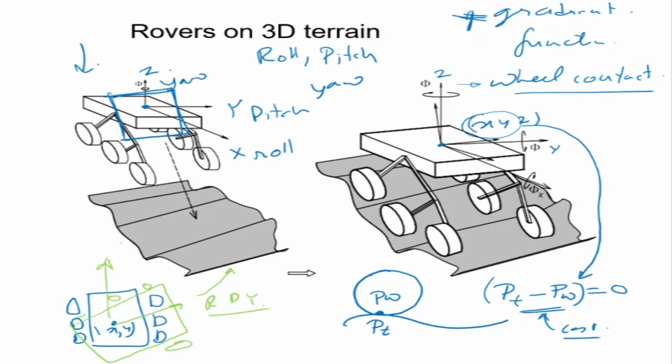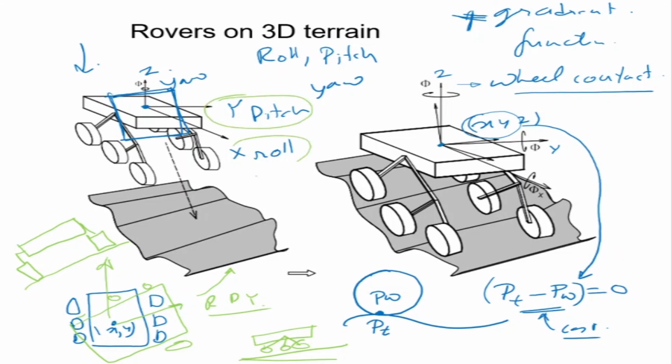What is it that we want? We want that the rover should not climb too much. One side has gone up, this is one wheel, and this is another wheel. This is climbing, so sideways it has climbed. In the front direction also, if it climbs, this can be a front direction climb, where 3 wheels are here. It is climbing like that. Again, the roll pitch yaw angle is there. So this climbing and energy would depend on the roll pitch yaw angles, especially pitch and roll. For different yaw angles, which is a bearing, it would have different roll and different pitches.